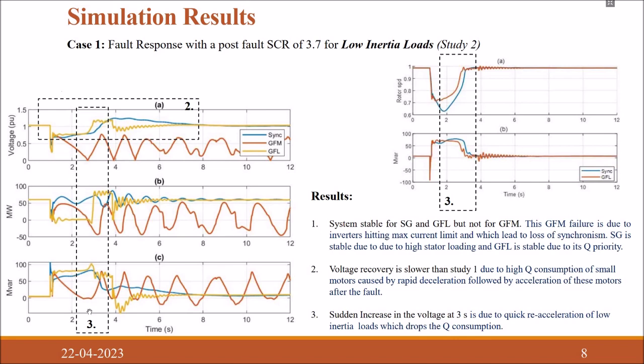The third result which we see is that at 3 seconds there is a certain increase in the voltage recovery. There is a certain increase in the active power injection of GFL, as well as a certain dip in the reactive power injection of the GFL. And this is because there is a quick re-acceleration of low inertia loads, which actually drops the Q-curve.